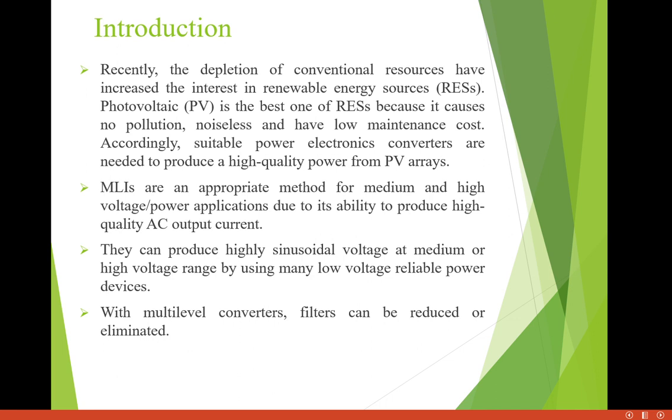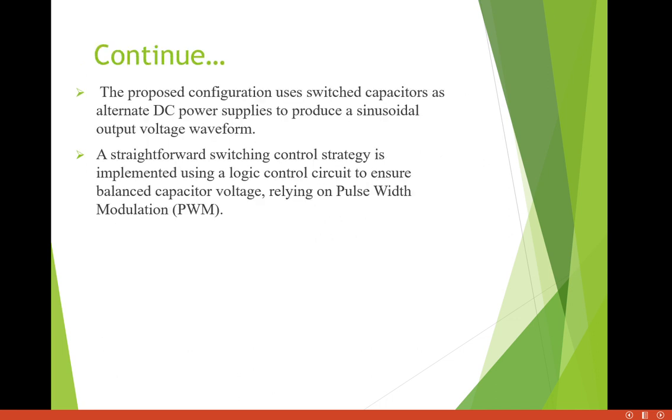Multi-level inverters are an appropriate method for medium and high voltage power applications due to their ability to produce high quality AC output current. They can produce highly sinusoidal voltage at medium or high voltage range by using many low voltage reliable power devices. With multi-level converters, filters can be reduced.